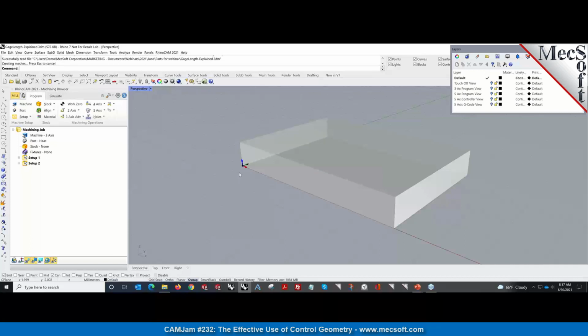In most CAD systems, this is the case. The world coordinate system coincides with the machine coordinate system, and so you don't have to do a lot of mental gymnastics to figure out where you're machining. But in parametric systems like SolidWorks, they have chosen the default sketch plane to be the XZ plane, and so the default coordinate system is not the typical machine coordinate system.